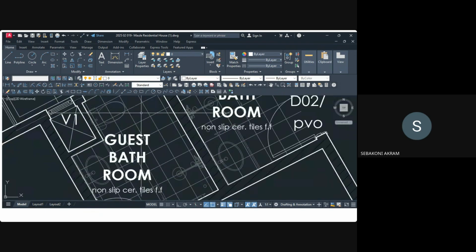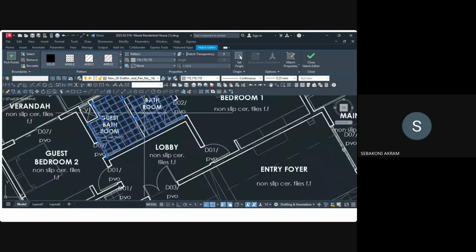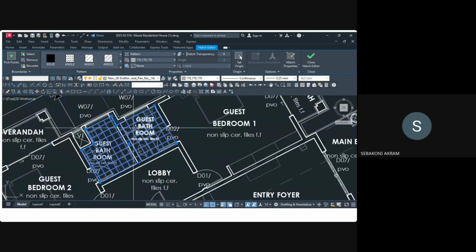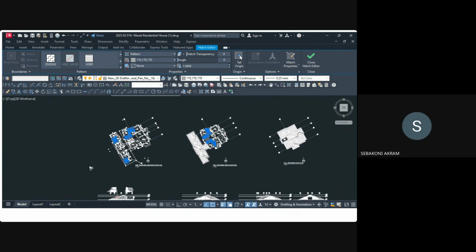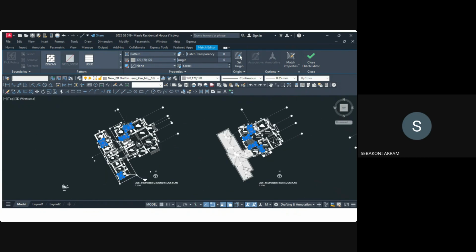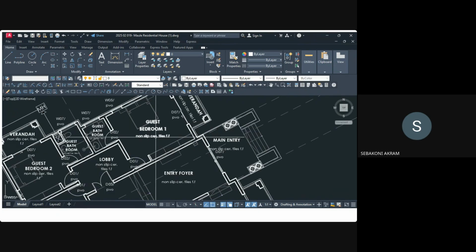There are these hatches that we really don't need. You can see those ones, because for us we do not need the detailing under the hatch. These ones are showing how the bathroom has the tiles. So we don't need all that. We delete, we select similar, and as you're selecting similar, zoom out and see what is being selected, so that you don't delete necessary information. Are we together, George? Yes. So we delete all that unnecessary information.